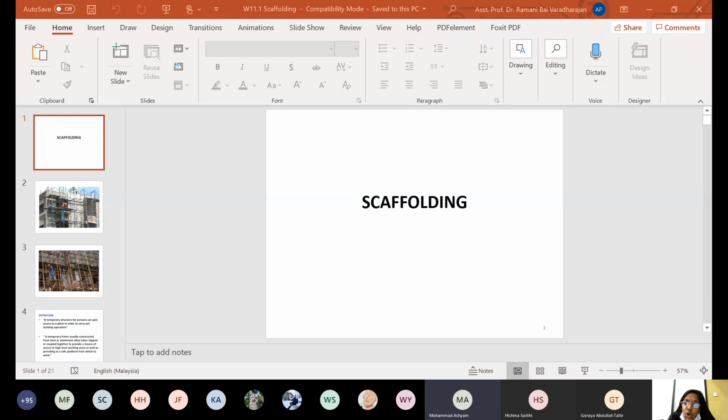Wood, very good. I thought of this. Wooden buildings in Sarawak, ancient. If you go to a museum, or even people are using it. Ancient buildings in Malaysia, most of the regions where it's always raining, they have to keep moving. The structure is in water, right? All these they build with wood because steel gets corroded, and concrete also slowly gets broken, brittle, and absorbs more water. But they use wooden pieces so that it is cost effective. They can dismantle and construct back easily, and they can move easily from place to place.